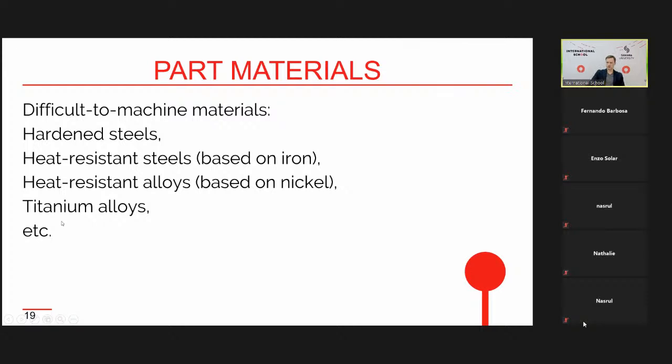And of course, these temperatures can be achieved when some engine works. For example, in rocket engines and in aviation engines, temperatures up to approximately 2000 degrees Celsius can sometimes be achieved. So the temperatures are very high in some parts of engines. I can mention that special techniques of surface improvement are used to withstand high temperatures. So not only the material itself withstands, but also some special treatment of the surface of the part should be used. Okay, the final group of alloys is the group of titanium alloys.